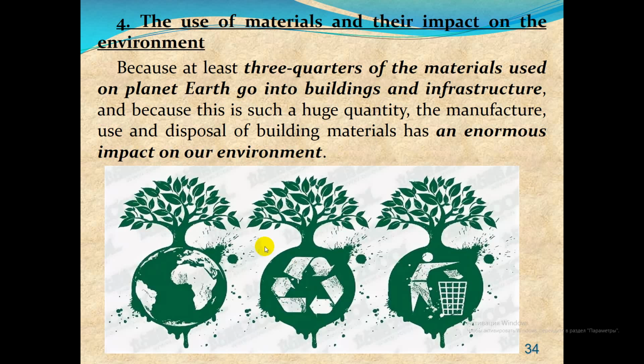Another factor that is sometimes overlooked is that buildings are static structures, and they are always under stress. A very large building will possess an enormous weight, and this load is carried by the structural elements and foundation. So, if the stresses vary in a cyclical way with time, they can lead to fatigue in metallic structural elements.